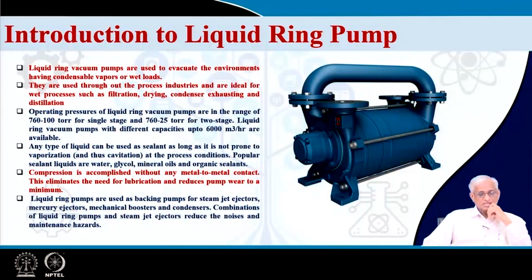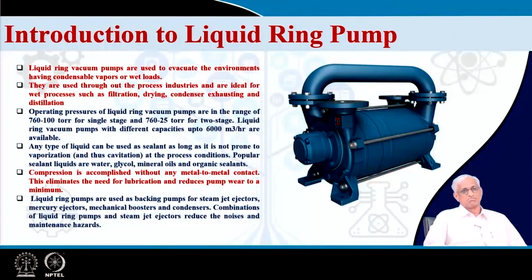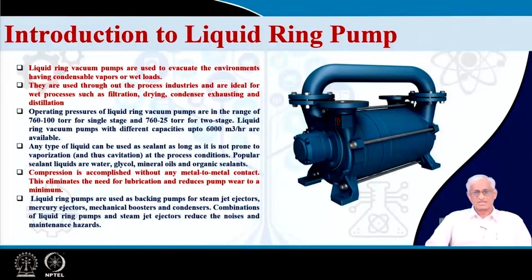And they are relatively simple pumps. Maintenance is somewhat easy and noise levels of course will be there, but with silencers etc. you can take care of that. And recirculation of the same water you can use. And if there is a huge amount of dust or something, you can filter it in some other loop.